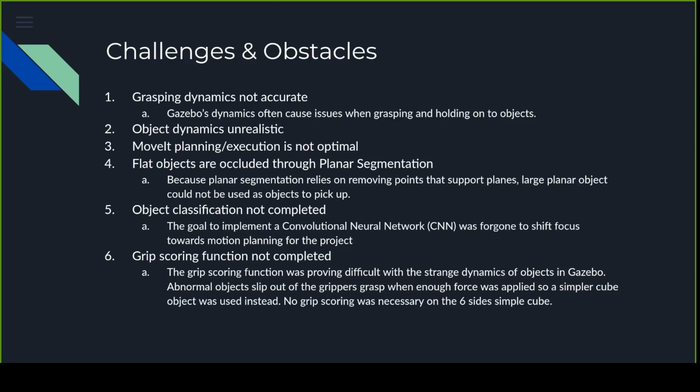One of the main filters we used for the point cloud filtering was the planar segmentation filter. The best part about this algorithm is that it filters planes, but it also poses some issues with some planar objects. If an object was considered too planar, it would occlude it from the results. So we ended up having to pick a large enough plane to occlude so that our smaller planar cube wouldn't get occluded from our results and could be picked up.